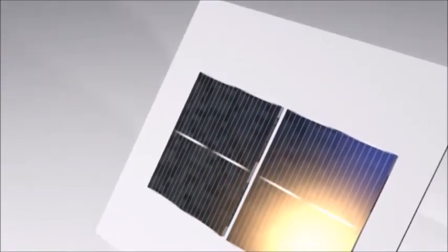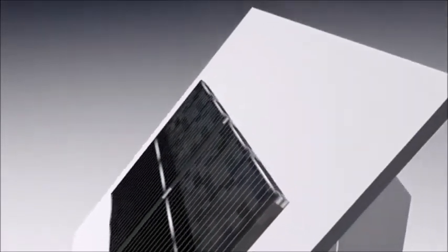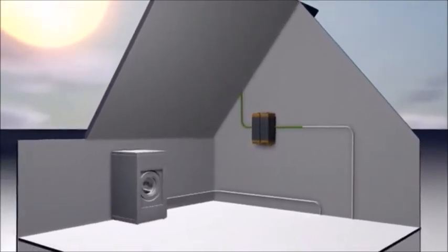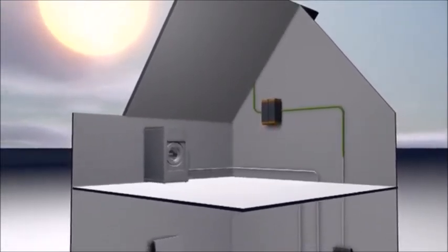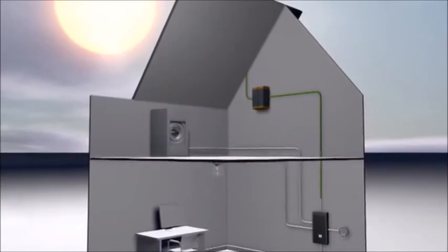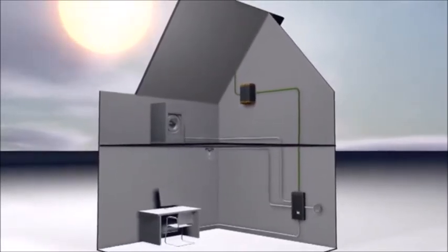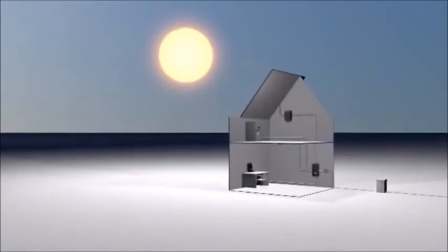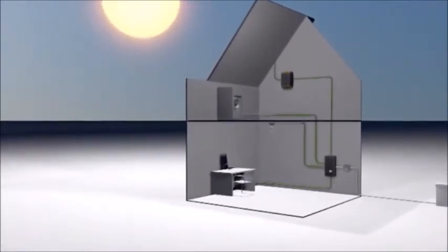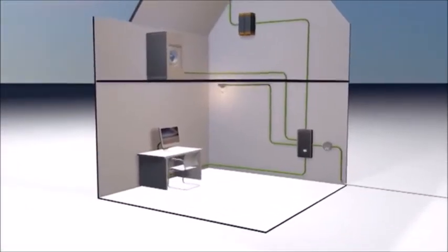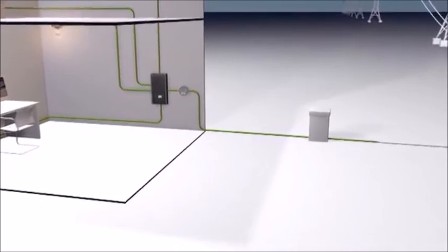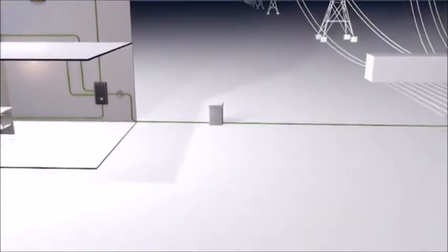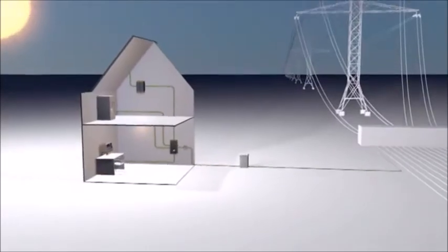On a normal day, with the sun out, the PV modules on top of this rooftop are busy converting the incoming irradiance into photo-generated power. The grid-connected solar inverters used in the system are also constantly converting the DC output of the solar module into usable AC power. The PV system is able to meet the load demand of the household. On a different day, if it's a very sunny day, the PV system is providing much higher power than what the load needs. Under such a condition, the excess power is fed to the grid. In most countries, the consumer can offset his electric bills in this manner. This facility is called net metering.